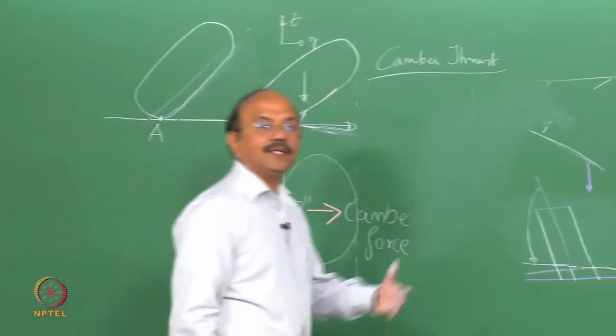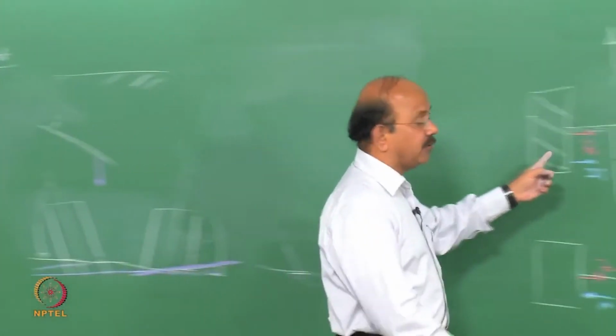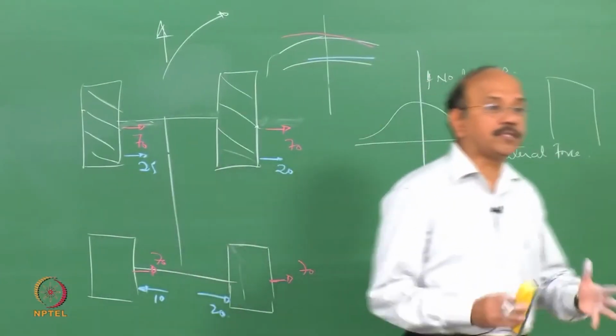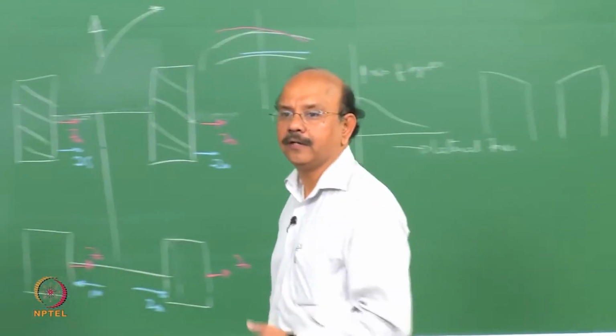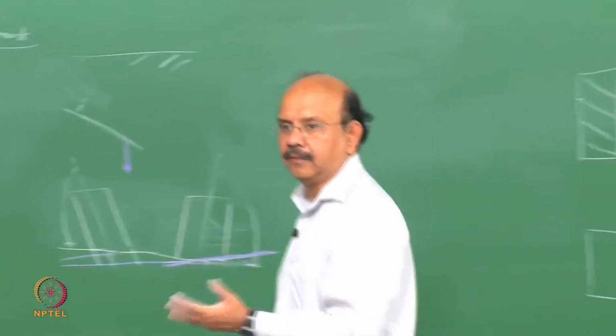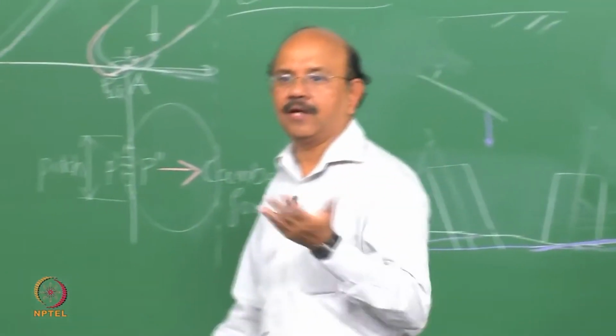So the tire manufacturers recommend that you rotate the tire, because so many forces are acting, you do not know the forces, and these forces have an effect on wear, and you want a uniform wear. Best thing to do is to have a rotation plan.